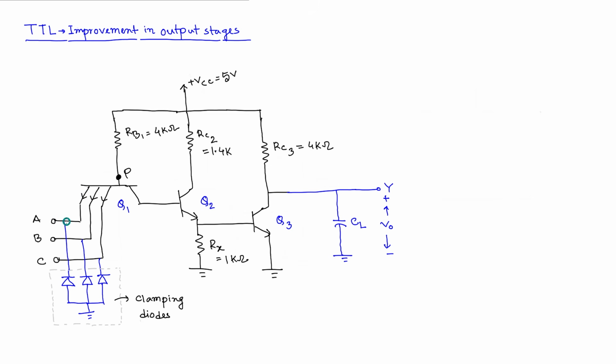So this particular junction here, whenever reverse biased, actually acts like a capacitor. How is that? For a capacitor, we know that the required thing is you need to have two conductors, and in between that we need to have an insulating material, right? So whenever we have a particular PN junction in reverse bias condition, already we will have a depletion region created here, and that will act like an insulating region, and we have the conducting plates here, right?